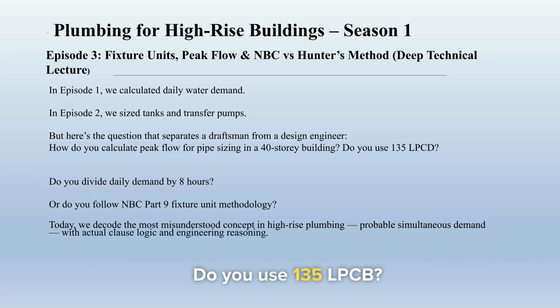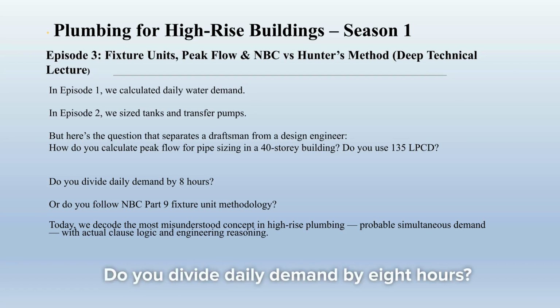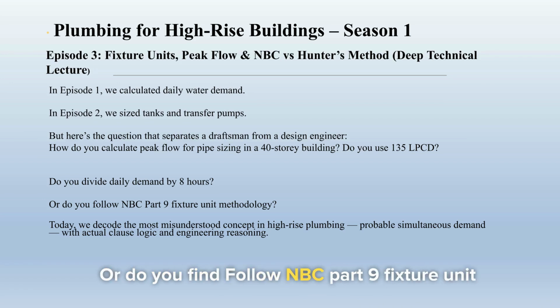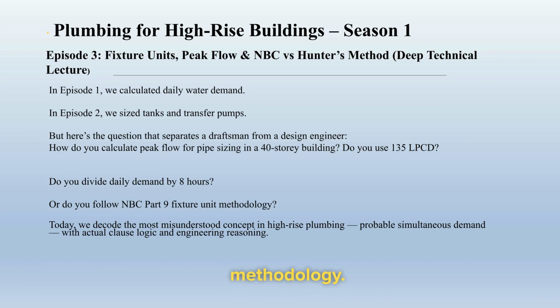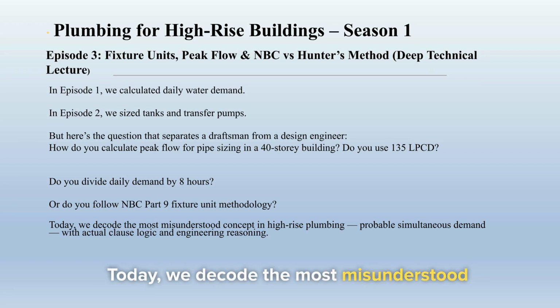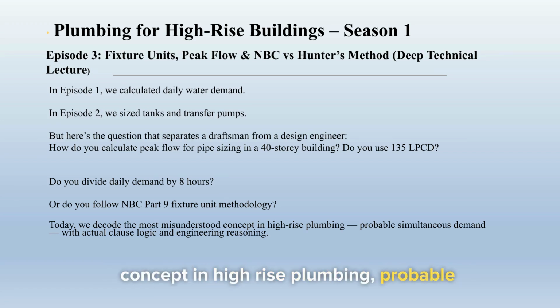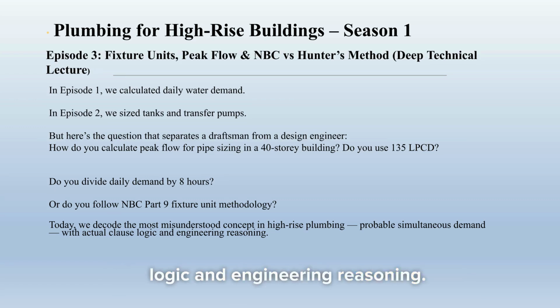Do you use 135 LPCD? Do you divide daily demand by 8 hours? Or do you follow NBC Part 9 fixture unit methodology? Today, we decode the most misunderstood concept in high-rise plumbing, probable simultaneous demand, with actual clause logic and engineering reasoning.